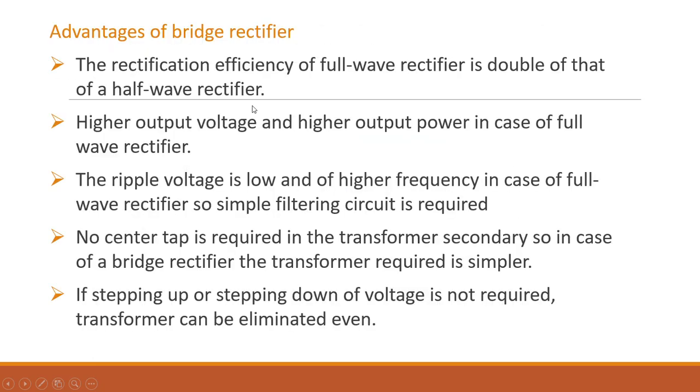And this is the advantage, that we are getting the whole secondary voltage at the output, and it gives higher rectification efficiency, higher output voltage, and higher output power, and it does not require any center tapped transformer. This is the advantage of the bridge rectifier.